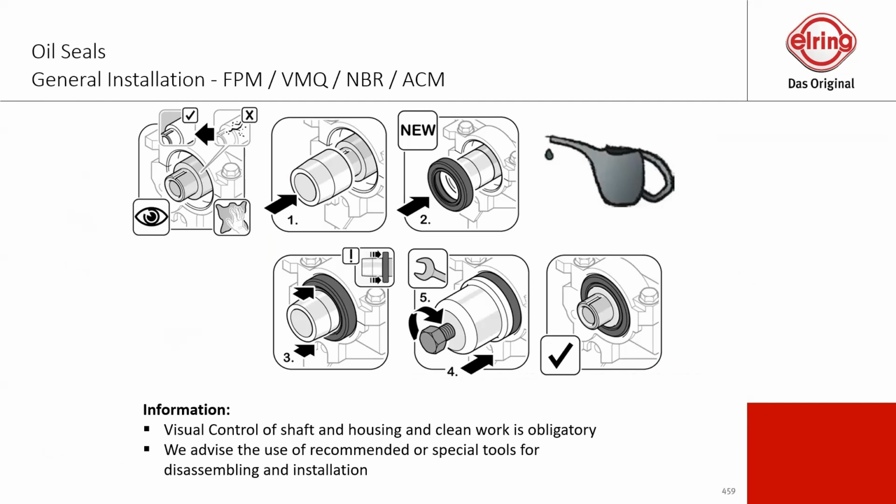It's quite easy and understandable, and I think all of you did this sometimes before. You have to check the shaft. It should be in really good condition, no dirt, no scratches, no defects visible. It's always recommended to use some protection tools to avoid any damage to the new oil seal. You put your oil seal over the shaft into the right spot. Use some lubrication, a thin motor oil.